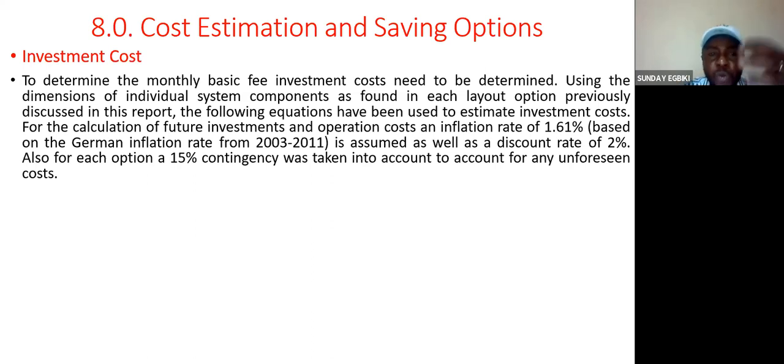That will help you to know the number of zones you have, the number of overhead tanks you have, the height at which you are going to put those tanks. And from there, you do your pumping system, you do your piping system. If you are using valves, you can include your valves and all those components. These are the general fundamental principles of designing a water distribution system.